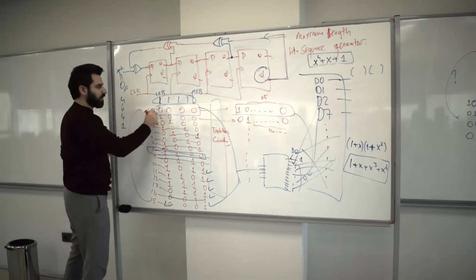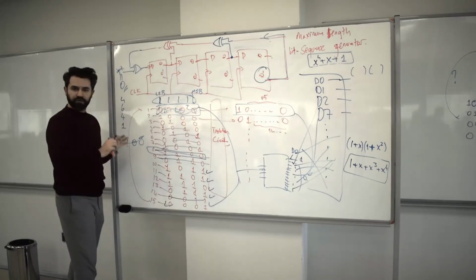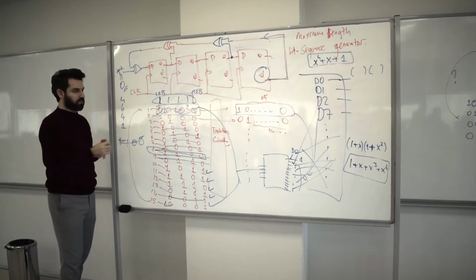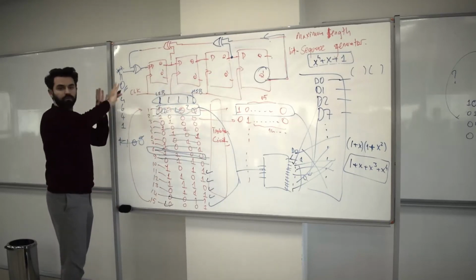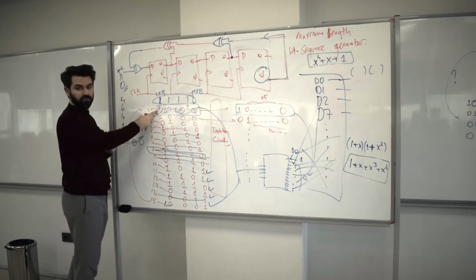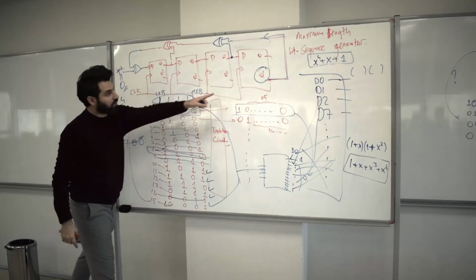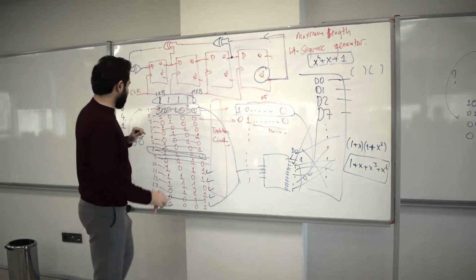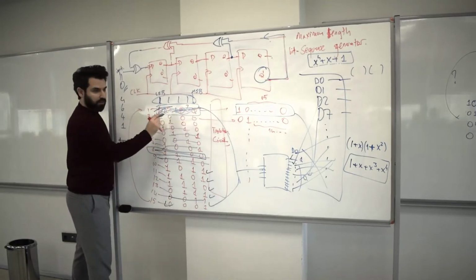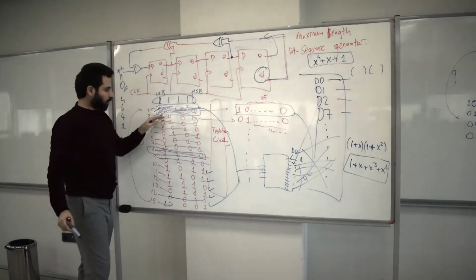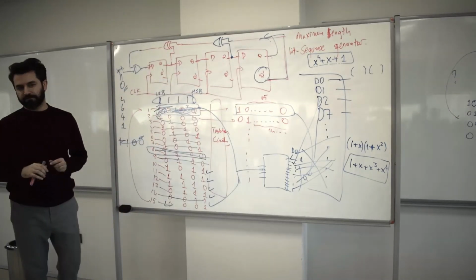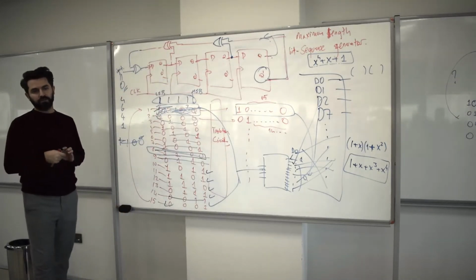That's why people sometimes exclude this and say if it is 15, then we're okay. Because with 0-0-0, you cannot count. Whatever you do with the XORs, you will never count with all these zeros. That's why I started with Q prime. But if you forget about 0-0-0, start with this one and then connect the Q, then you will realize that all 15 possibilities will be counted. Okay?